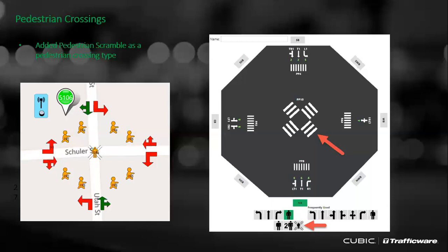And the last one: on the split history report for the 85th percentile value, does it neglect any zero split? We're trying to time the signals. Yes, if there is a zero split, that means the phase was not even active. If you have only 4 phases programmed, you will have all the remaining 12 or 28 phases, depending on which controller you're using, showing zeros all the time. So there are no values for that. That means the split was not even assigned for that particular phase or that particular time.